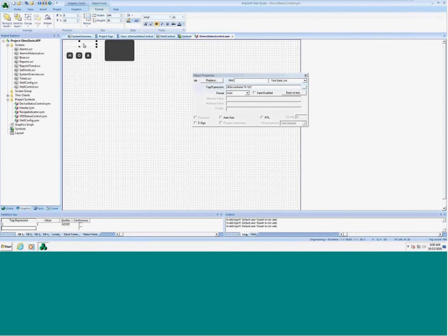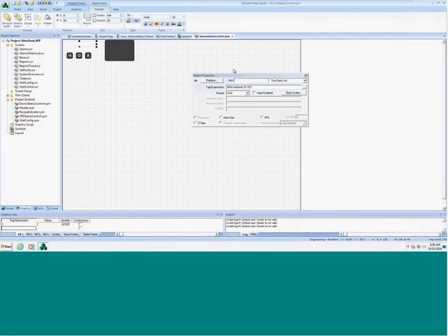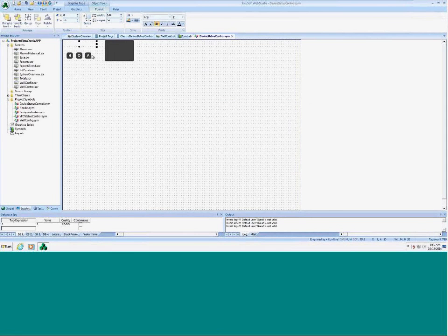Here's the device name. Any tag or expression that you want to pass in as a property, you use this pound indication, and then this device name is what gets displayed over here. Then you have the colon and then a default value. So I just put in a string in there to begin with. So that's how you can pass in a simple object, a simple tag type. To get a class tag, if you just pass in the whole class tag, the value of the class tag itself is really a string of its name.